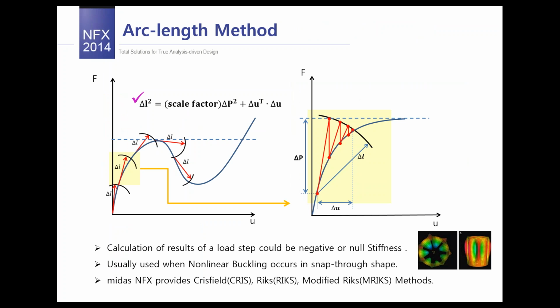As you know from the previous webinars, the Newton-Raphson technique provides an incremental solution, but this method is very poor for buckling problems because the slope at the limit points is exactly equal to 0. Which means the slope at this point will be horizontal, and simply it's not possible to converge.